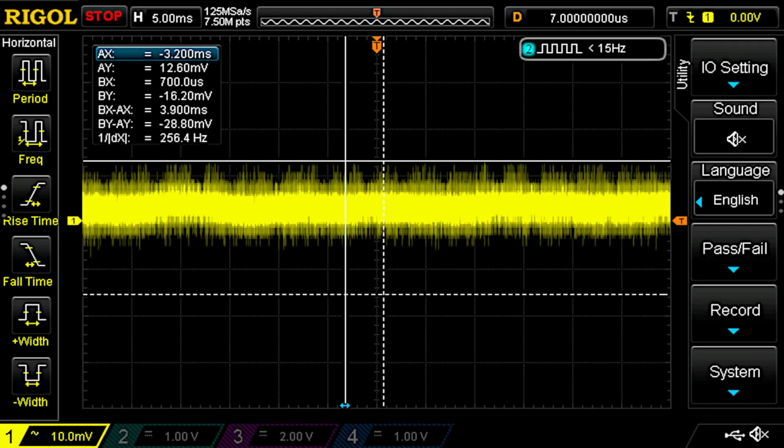And finally, the waveforms at the ADC input pins. I do have the current load terminals shorted for this. First, the ADC input for the voltage sense. From the input terminals, it goes through a resistor divider and then an op-amp buffer. So I think that looks pretty good.